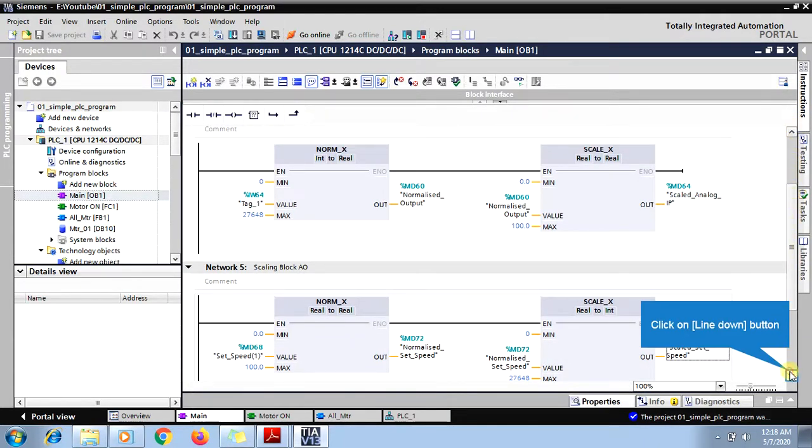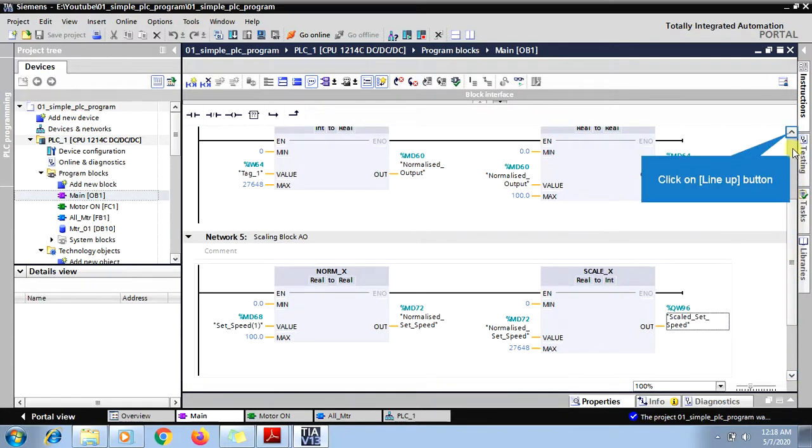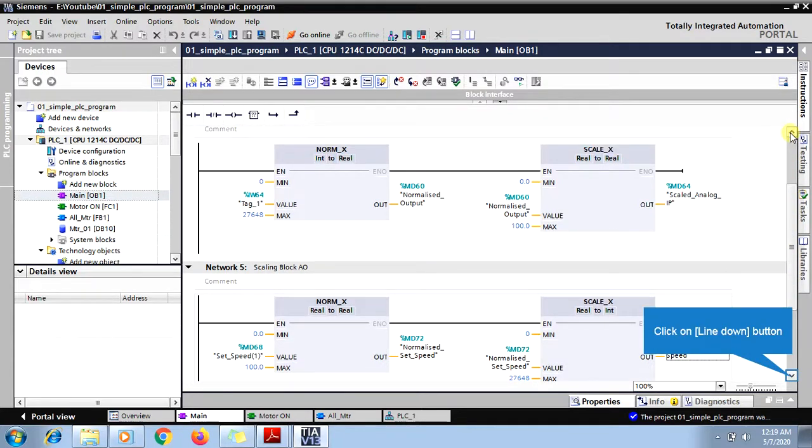You will have the same procedure to be done using either adder or subtractor block. It's the same as y equals mx plus c. Okay, so as we know, analog input is having counts, it is 0 to 27648. So if my current is 0 to 20 milliampere, how will the output change? When there is 20 milliamperes, I will get 27648 counts. When it is 0 milliampere, I will get 0 counts. In between, I can get 13,000 counts. That means the input will be 12 milliamperes.